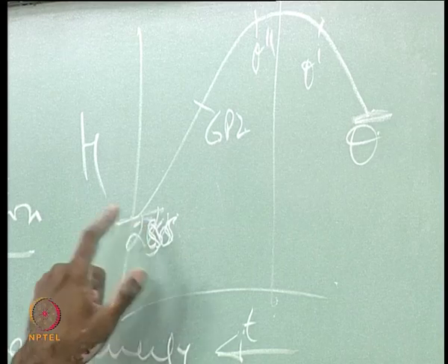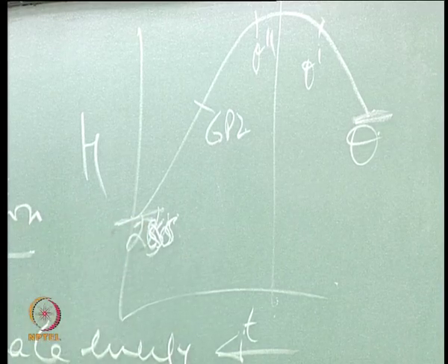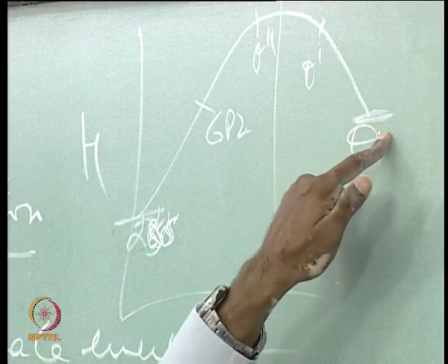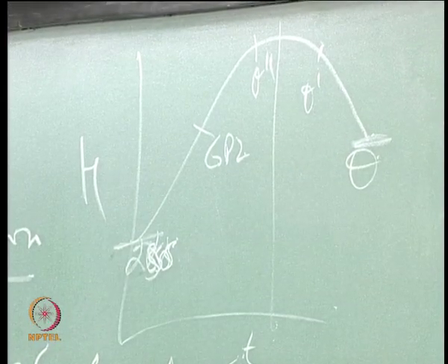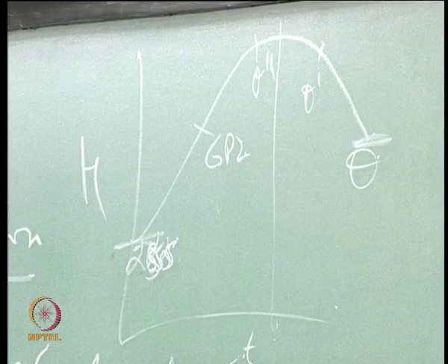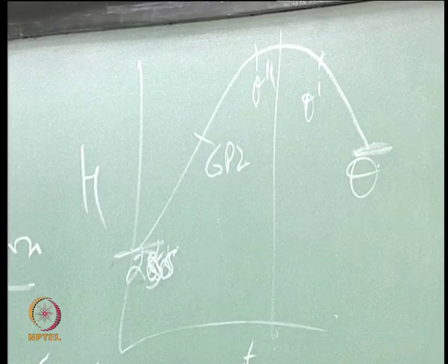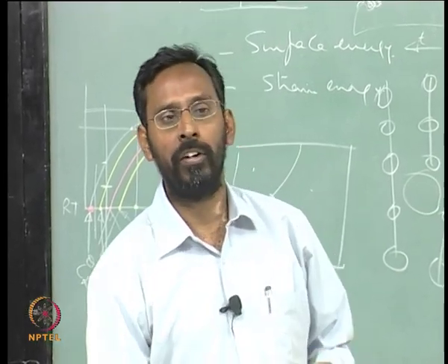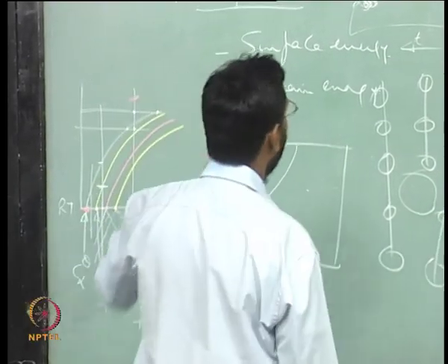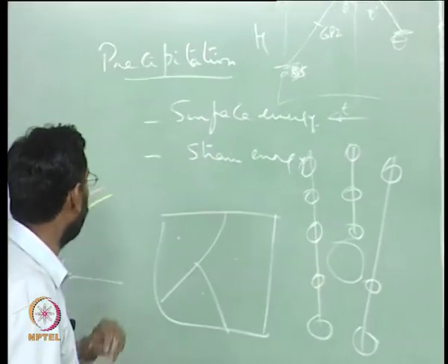In this case it is only solid solution strengthening, whereas here you have precipitates, and there the precipitates are larger, and the only strengthening that comes is by formation of the Orowan loops, by the bending of the dislocations, not by the cutting of the dislocations. So that is another aspect, let us not go into the details of it.